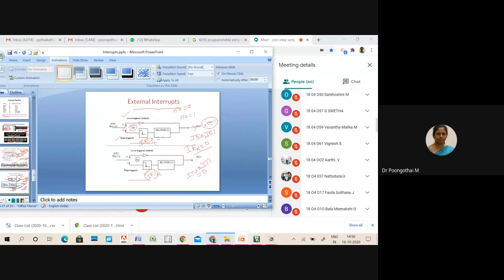So upon an edge triggered pulse on INT0 and INT1, your 8051 sets the IE bits in the TCON register, that is IE0 and IE1. After the execution of the RETI instruction, that IEx is cleared.